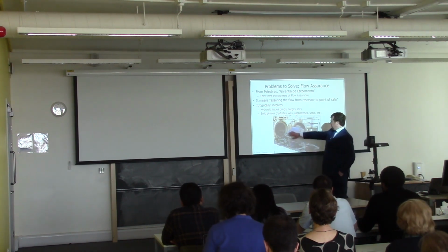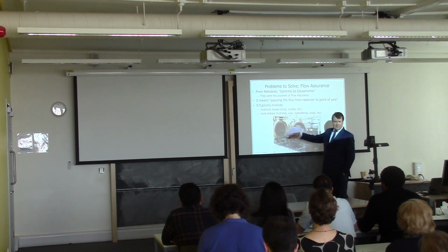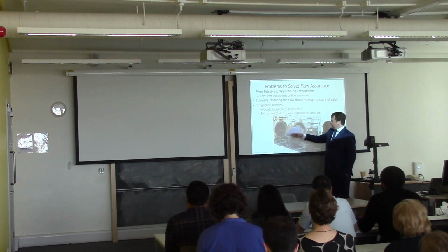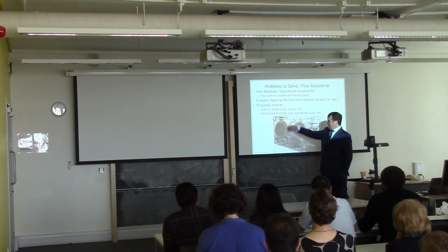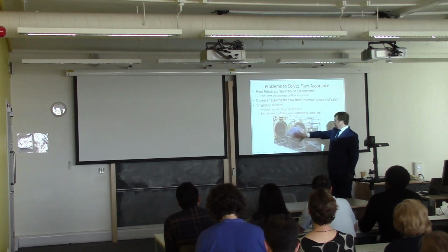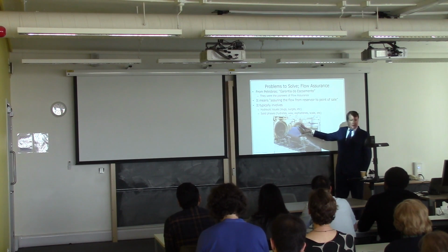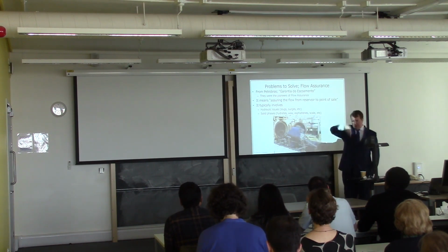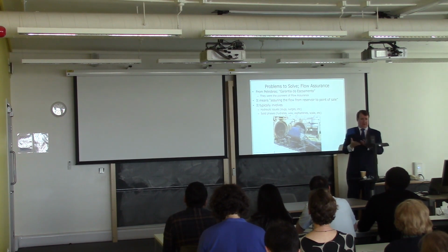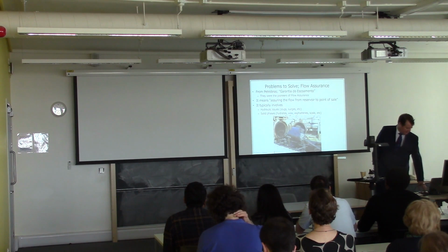These are solids that can precipitate in the pipeline. Here's an example, a nice picture. Everyone shows, when they do a flow assurance presentation, a picture of some black gunk coming out of something. And this is some wax that fortunately has come all the way through the pipelines and arrived in a vessel that they could clean out. But imagine if this big lump of solid gunk was actually 1 kilometre down and 5 kilometres that way in a pipeline, it's much harder to actually get to and clear out. And that's the problem, we want to avoid that.